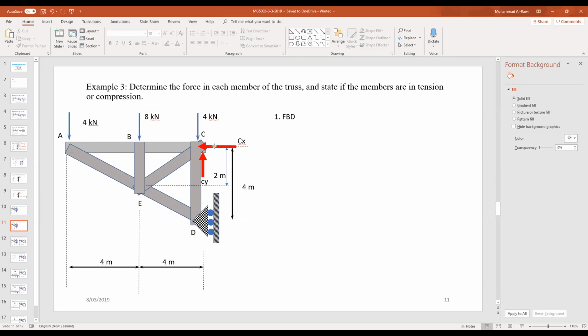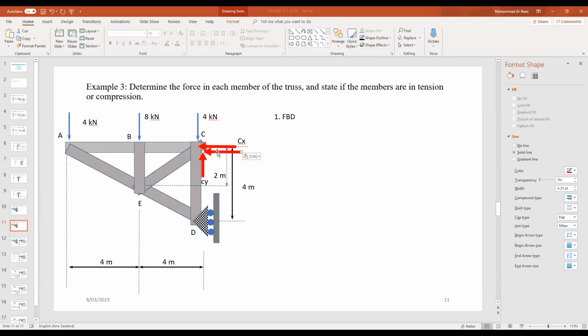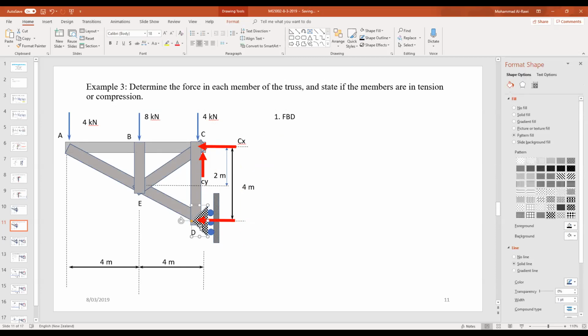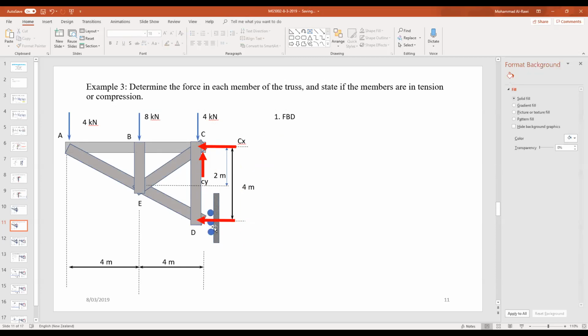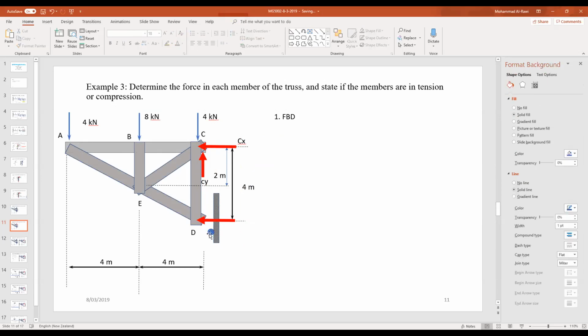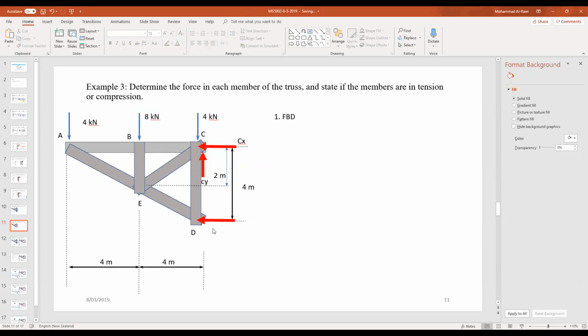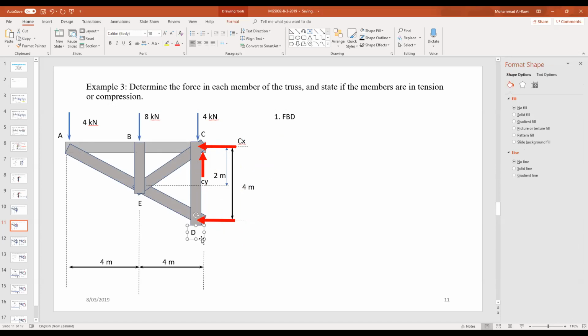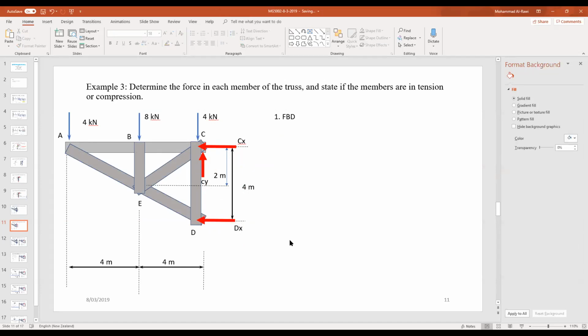All right. Simply, it's a roller. Remember the chair we did in the class? The wheel is only touching the floor with one force. Even though they show 3 wheels, we treat it as one. So you remove all this together and it's treated as one support reaction, which we call DX. Very easy. I'm trying to confuse you here with things, but that's how they look. So it's only one force, DX, in the x direction. There is no force in the y direction.